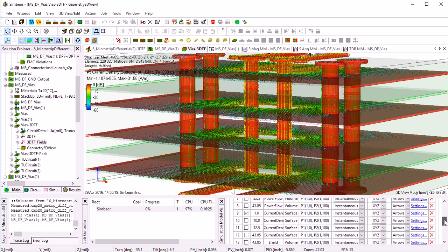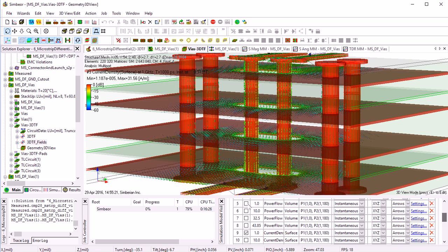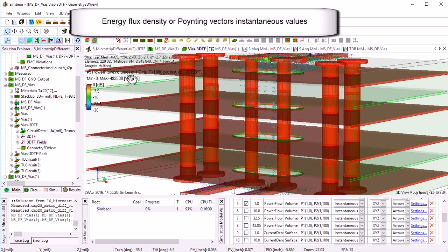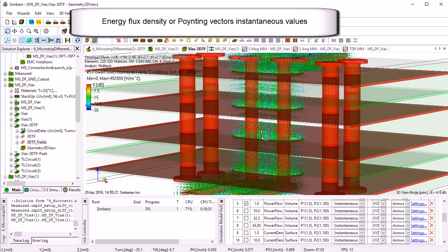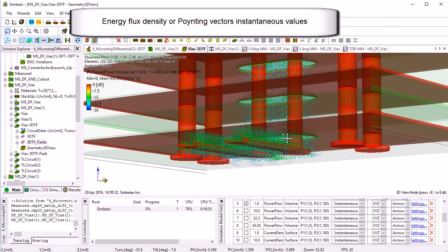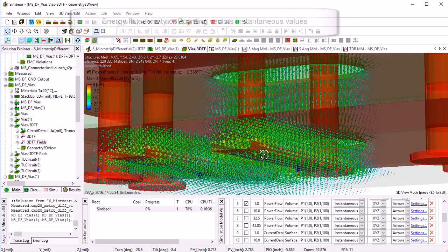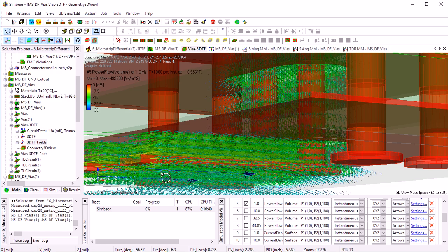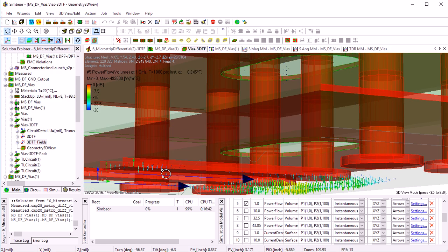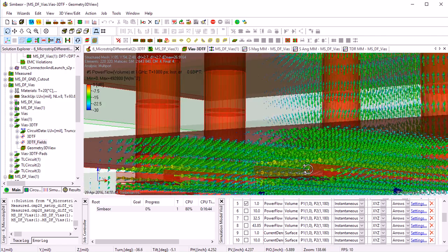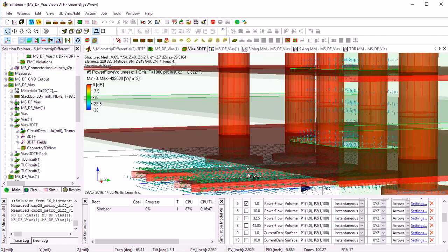What about the power flow? At 1 gigahertz, again logarithmic scale relative to maximal value in watt per square meter. We can see that the power from the bottom side gets in the same direction. You can see the current was flowing in the opposite direction, but right here you can see that power flows under both strips in the same direction. It's for differential line.